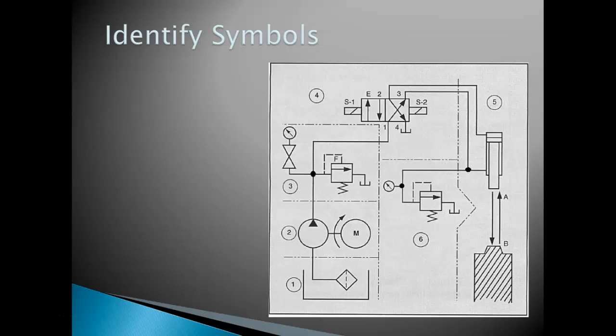With fluid being non-compressible, if you put it at too high of a pressure, you risk blowing your seals. So the way we have gotten around that is by putting in pressure relief valves. Because what those do is direct any excessive pressure and fluid to where? Sends it back to the reservoir. Okay?